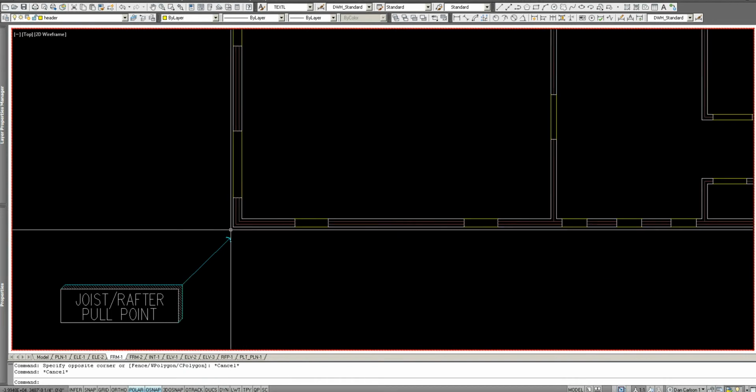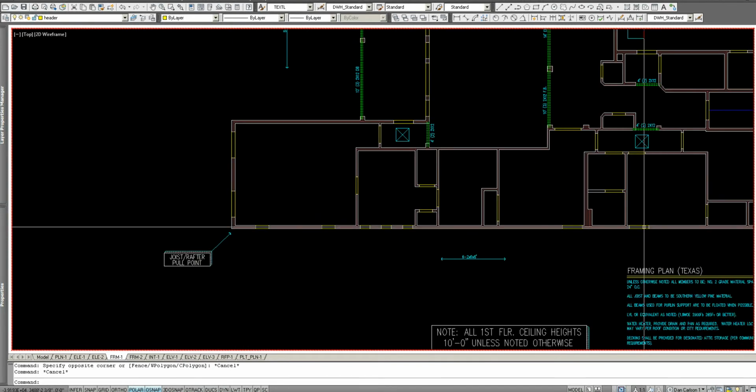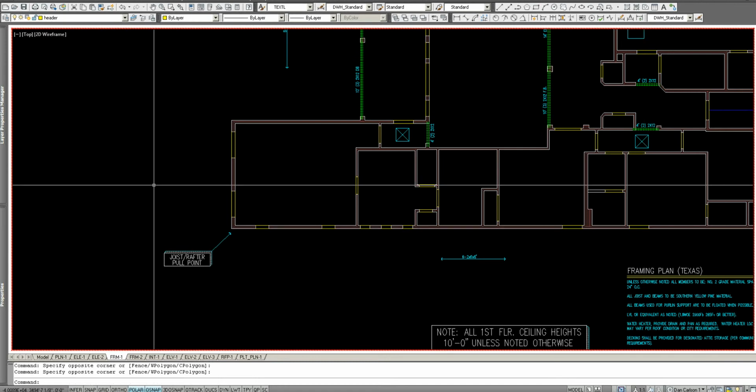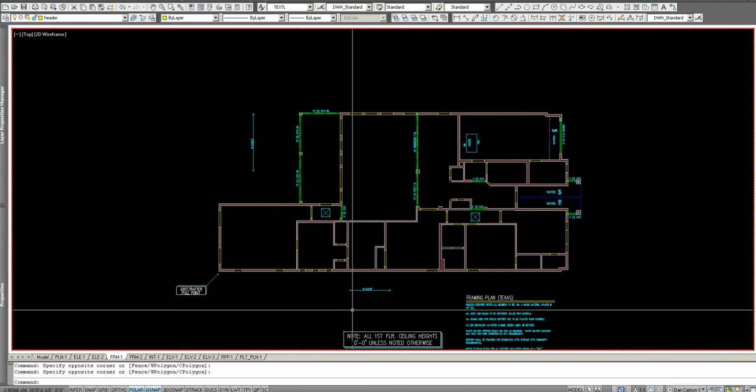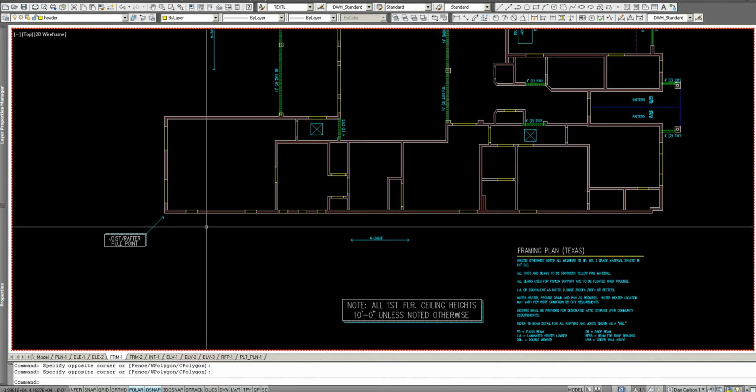So we're going to start back in this corner and move our joists across the house. Alright, so this is where you'll need your little span chart list. Everything on this plan is going to be done on 24-inch centers. If the span chart does not meet 24 centers, then we'll do doubled 24 on center, which is basically the equivalent of 12 inches on center when you look at that span chart.